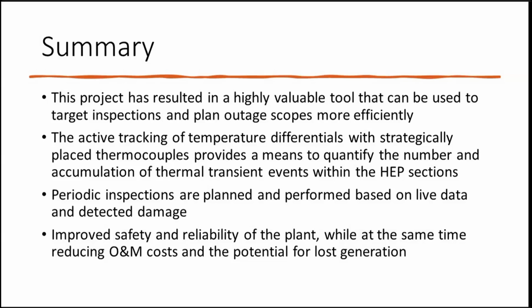You prep the tube, and then they're able to zap them on using this technique. And then the way you route the thermocouple wire, wrap it with insulation, and secure it with tie wire, and the type of thermocouple wire you use is all specified in there.